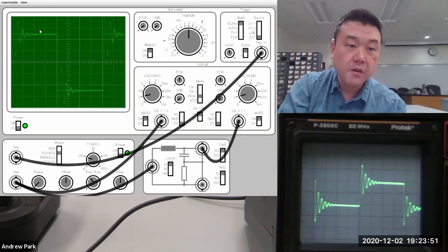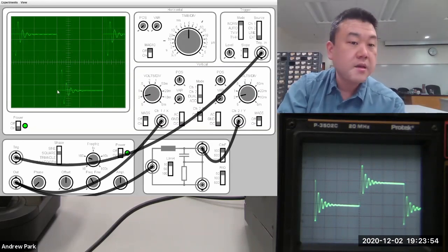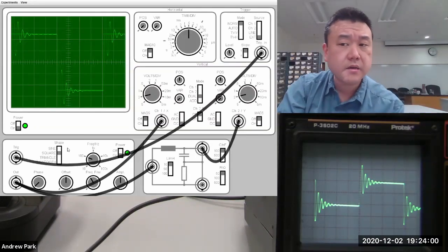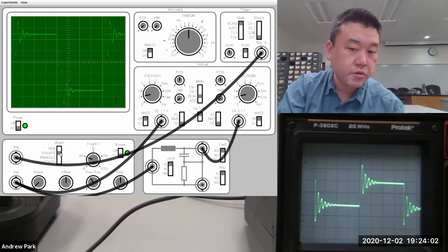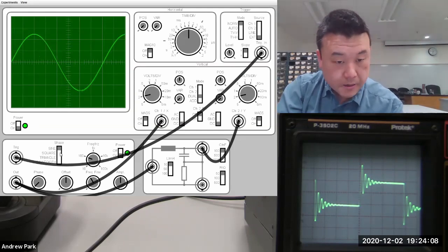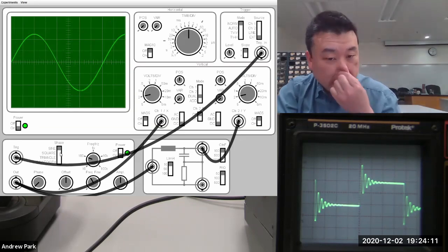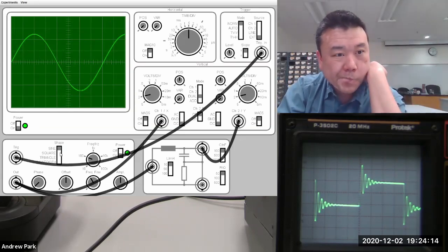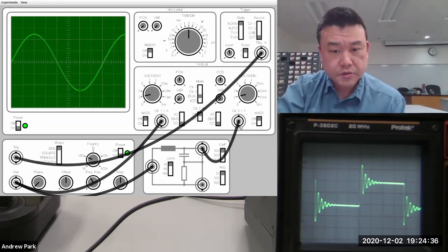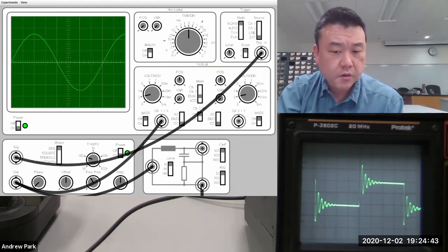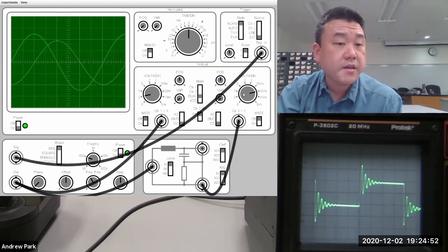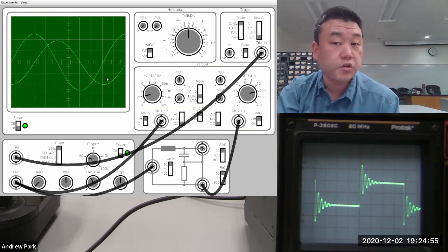With the square wave, all I'm doing is basically applying a sudden impulse and seeing the circuit response. What I want you to see is an AC circuit. With the AC circuit, you need to have a sinusoidally driven source. Let me see if I can demonstrate something here. One thing I can demonstrate in simulation now and also in the circuit is this: I'm going to measure the voltage across the resistor. This way, what I measure will be a representation of current, since it's proportional to the current.